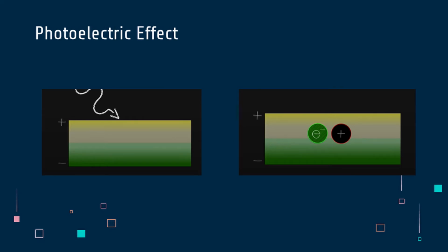The photoelectric effect describes what happens when a material is struck by photons. In a photodiode, when photons with a specific wavelength hit silicon, it forms a pair of an electron and a hole. The electron naturally migrates towards the positive side, and the hole migrates towards the negative side. Thus, the presence of light can be measured by the voltage on top of the photodiode, and different voltages would represent different intensities of light.